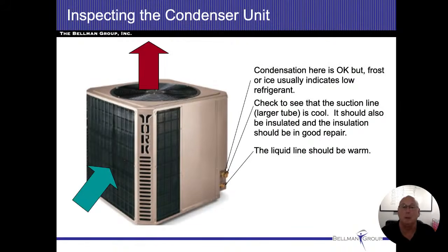And let me just be clear. Very few people ever go to that extent. There are always simple steps that you could do with air conditioners, and there's even more. Testo makes a great temperature reading system. As we're looking at the condenser unit or the compressor cabinet, again, it's the same thing, just different words. On the bottom there, we see the refrigerant line connections, so the thicker line and the heated line. We can put thermometers on those, and figure out what the temperature difference is, or the delta, and that'll also tell us if the air conditioning system is working properly.